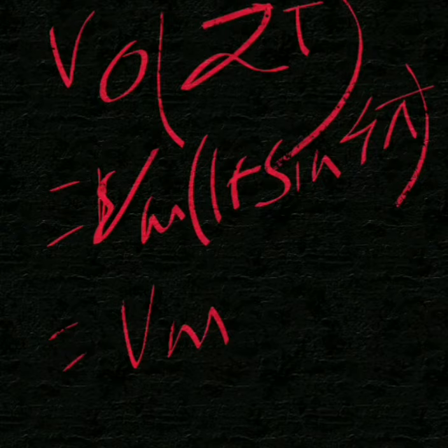All these values imply that after 3T by 4 there is no negative value of output voltage, that is, after this time instant the applied signal is positively clamped. Now these values will be helpful for drawing the output graph.